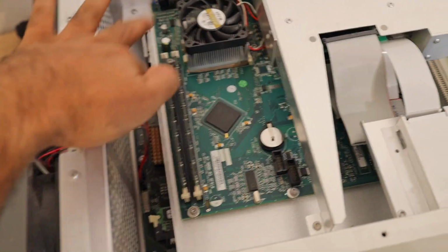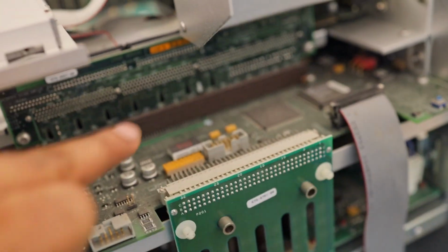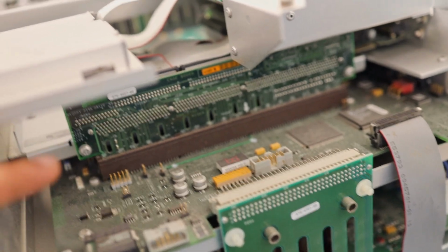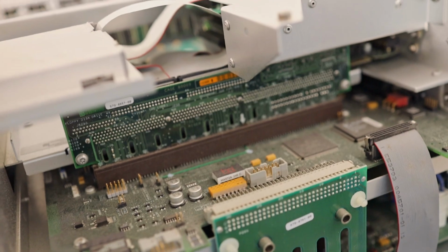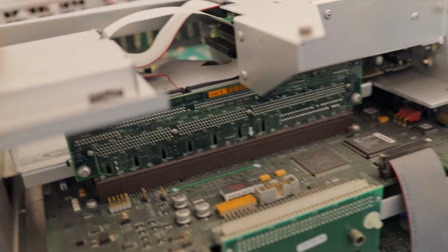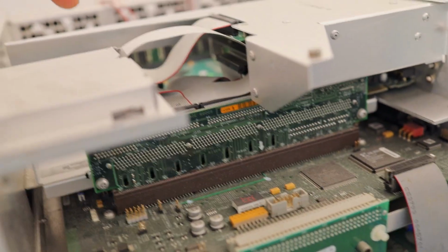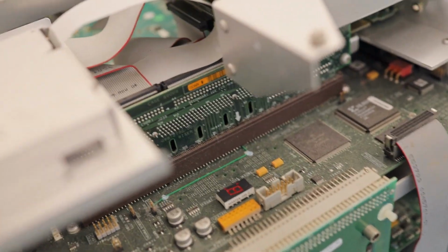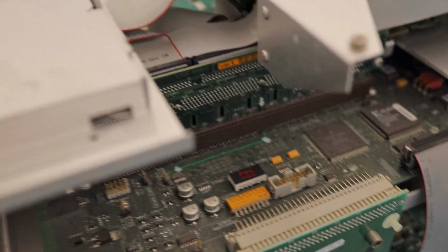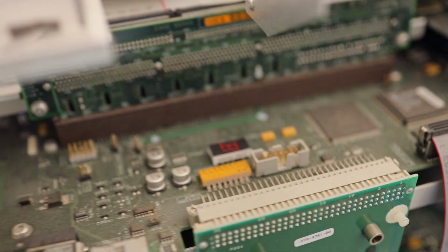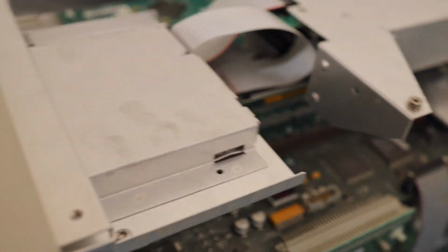This runs Windows, and these two boards need to communicate, and they communicate using this little PCB. I have read on the internet quite a bit about this series of oscilloscopes, so I know how they are built. Some of them also get corrupted CPLD, but most of the time it's corrupted RTC, which causes it to forget its boot setting, and this secondary board doesn't boot. Primary board boots, but secondary board doesn't boot. And this is a little single segment display. It shows you the board status of the VxWorks board, and we will try to power on the board and see how it behaves.